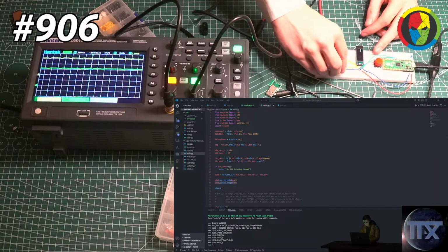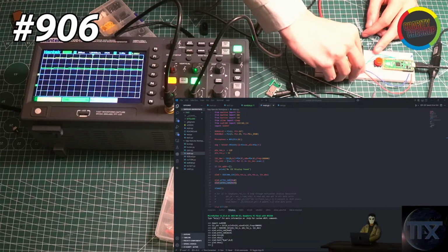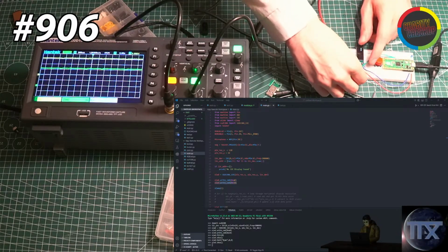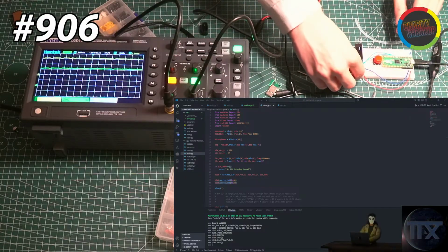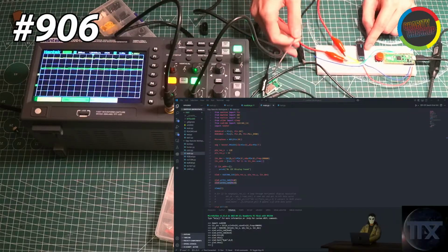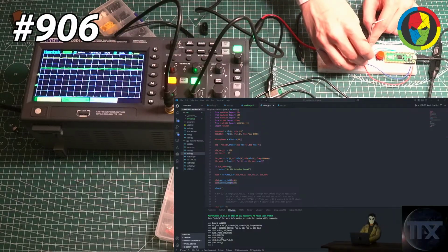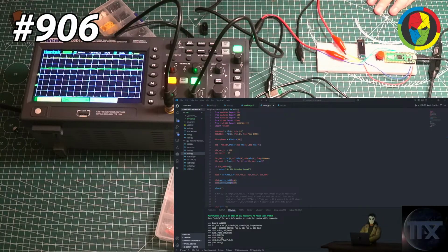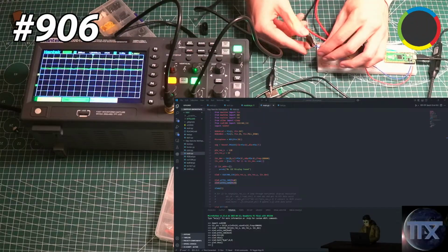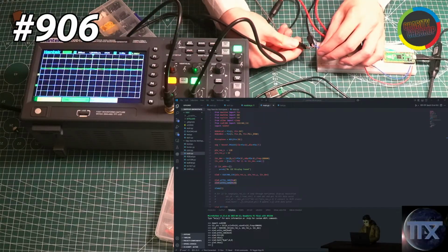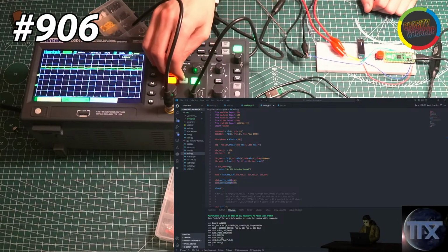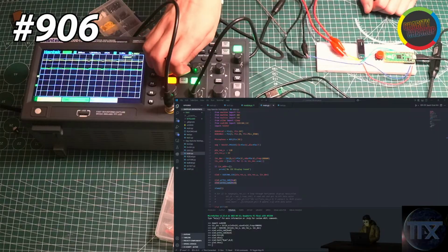That makes sense. That's why you can connect them all to a single network, and you can connect 128 together with one wire. I really like that feature of I2C. I imagine I will eventually grow to love I2C for that precise reason: you don't need to bother with connecting everything in different places. Not a single multiplexer, just every single device on a single wire. And usually you don't have to worry about speed, right? I2C is a communication protocol where you're not transferring large amounts of data like audio or video. You're just doing text or commands.